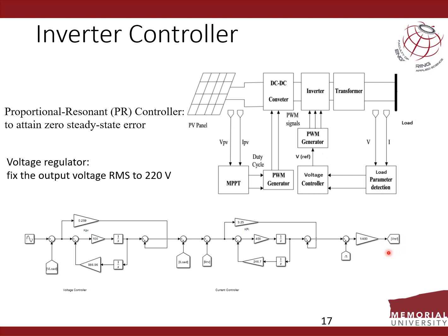Comparing with some signals, the PWM generator will use this reference as a signal to feed into inverter as a gate signal, controlling the on and off state and regulating the voltage on the load side.